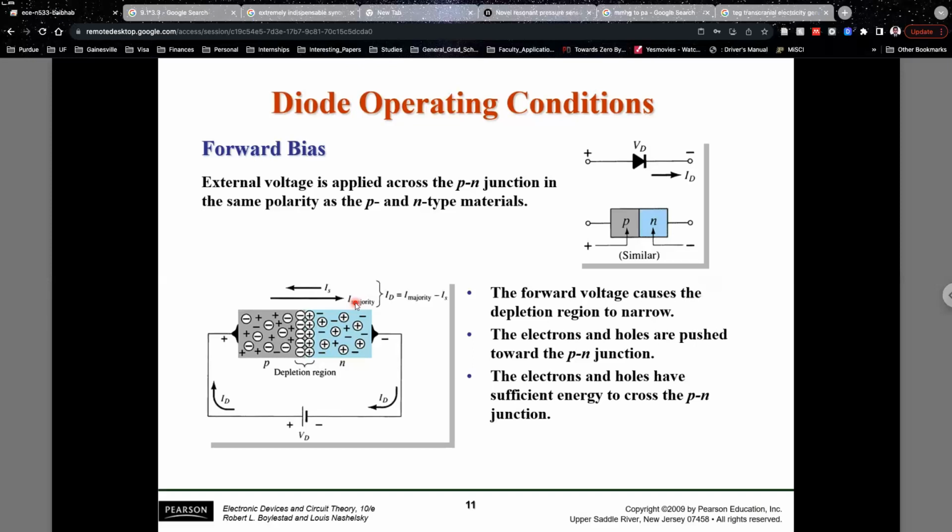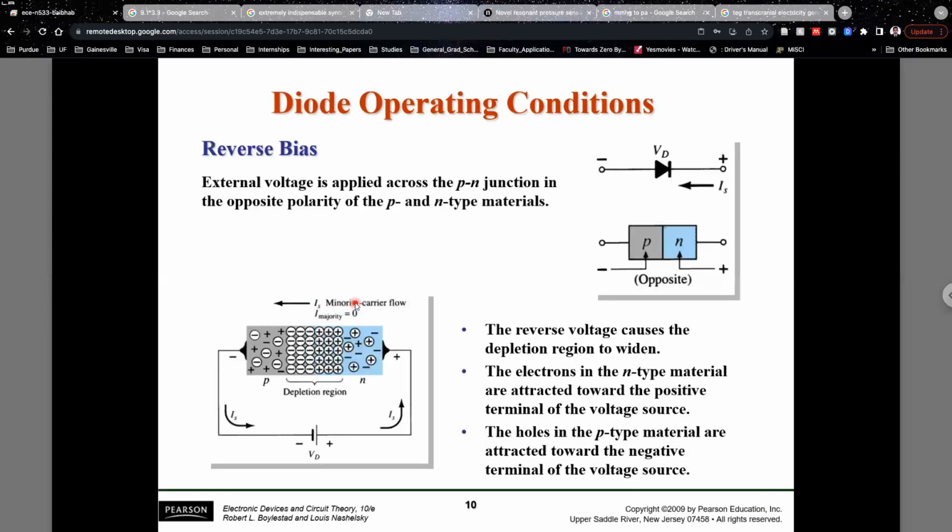Okay. Questions? So for the reverse bias, if you had a current meter, you'll see zero current. But yes, if you can monitor the expanding of the depletion region, that will happen in, let's say, nanoseconds or microseconds. So you're right, theoretically, if you can monitor it for nanoseconds in the beginning, when you're just applying the negative bias or the reverse bias, you'll see that initially there will be a small amount of current flow and then it will stop.